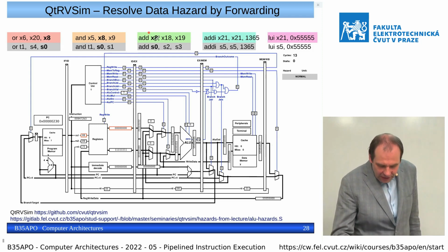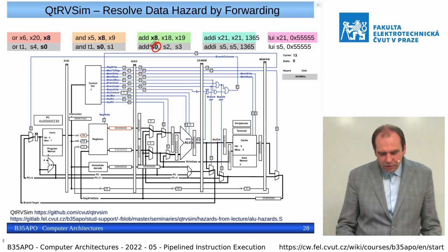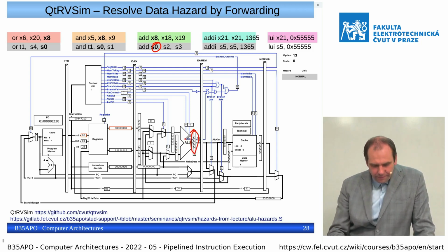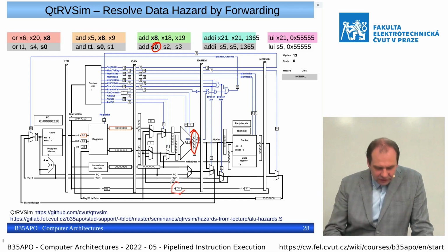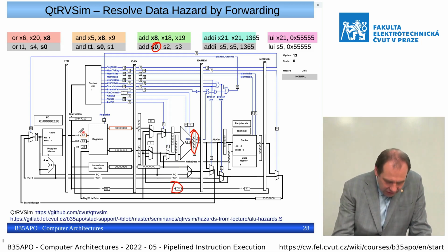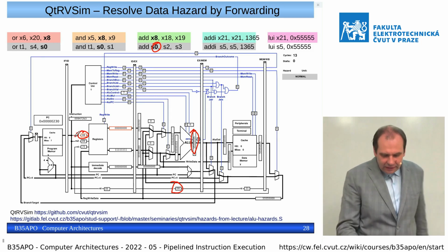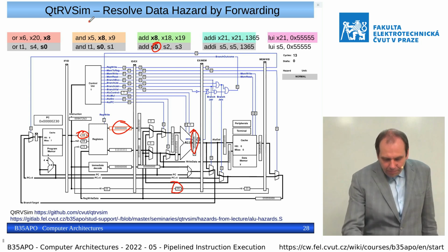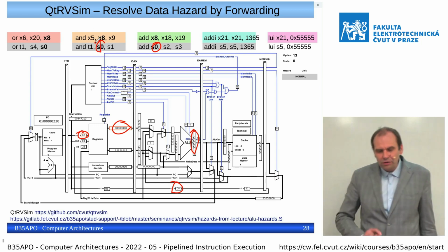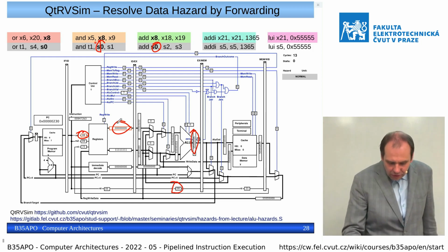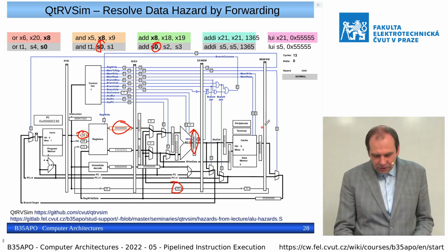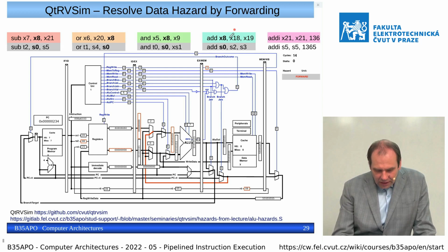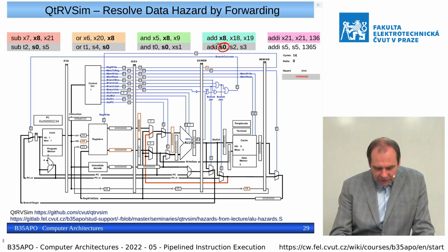So in this case, we have the instruction add of 222 and 333 to the register S0. We know that S0 is our register 5. It matches the value which is selected as the register which is read at the decode stage. But in this case, we do not stall the CPU, but continue with the incorrect value read from the register to the next clock cycle. And in this case, the addition propagates to the memory stage.